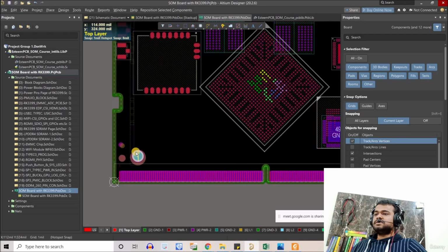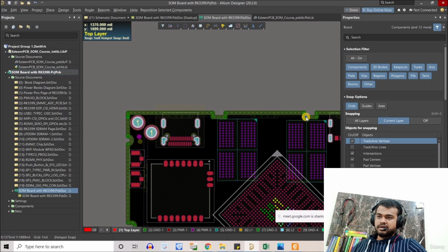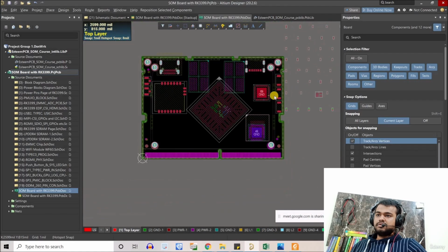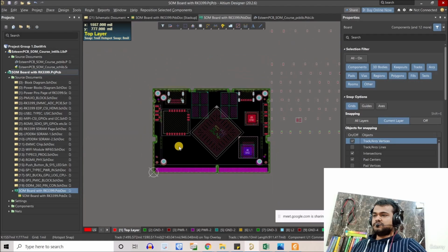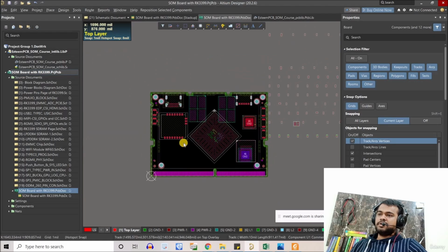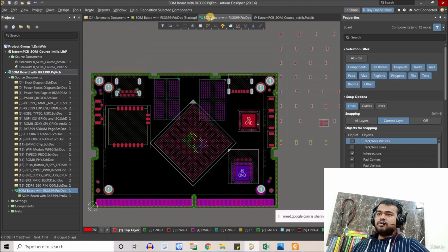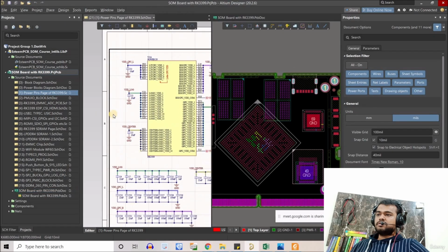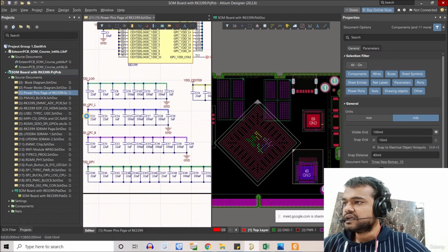Everything will be placed inside these shielding markers, apart from these antennas and a few switches, because those are just normal connections. We have to pack every high-speed signal inside its shielding. That is one thing. Let's start with the component placement. How to do that? It is simple. Just target one block. Let's start with CPU_L, and where is that? We have these capacitors here. Just select those.